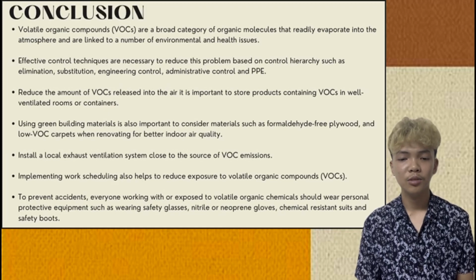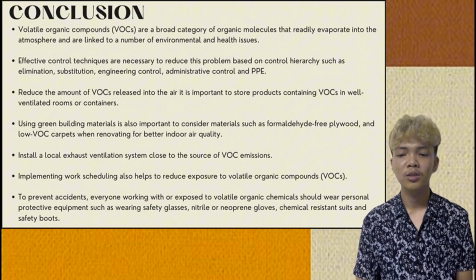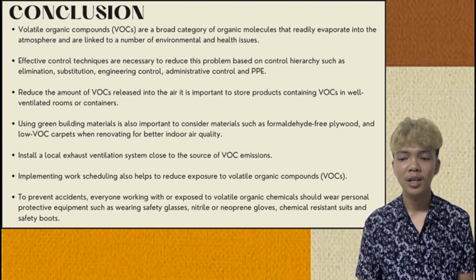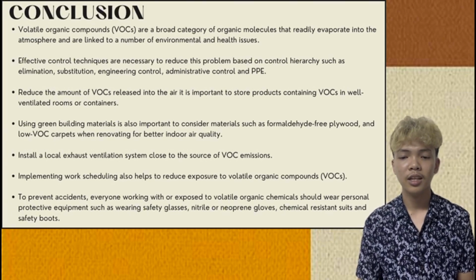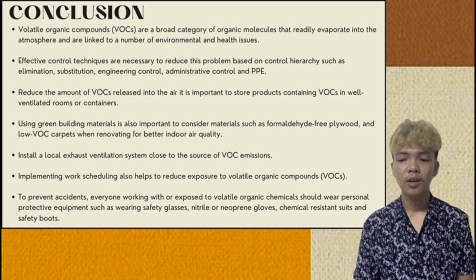Last, it's to prevent accidents. Everyone working with or exposed to volatile organic chemicals should wear personal protective equipment such as safety glasses, nitrile or neoprene gloves, chemical resistant suit, and safety boots.